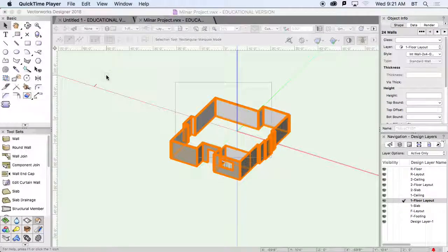Okay, so I have my first floor walls drawn here. They're all in the location where I want them to be, right? All our dimensions we measure to the outside of the sheathing. Now, I don't want to have to redraw. So in doing your second floor, you should have duplicated these walls and sent them to your second floor layer and made whatever modifications you needed to.